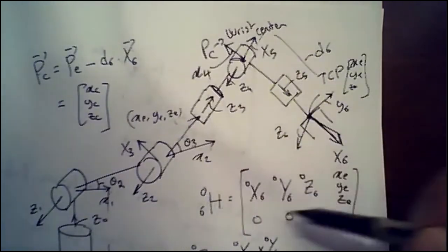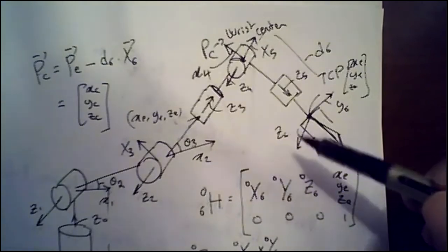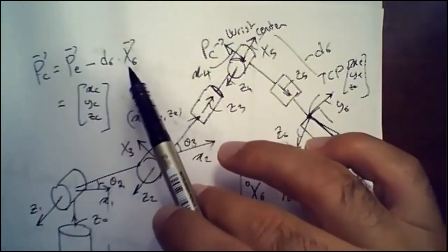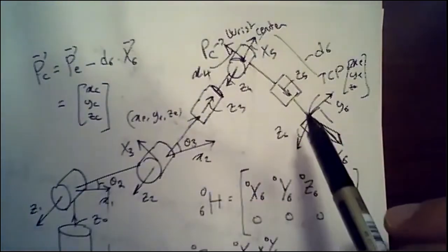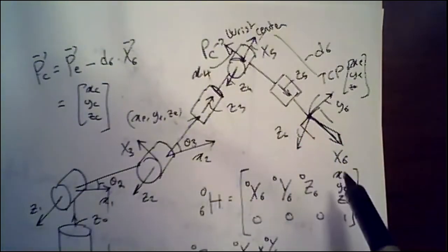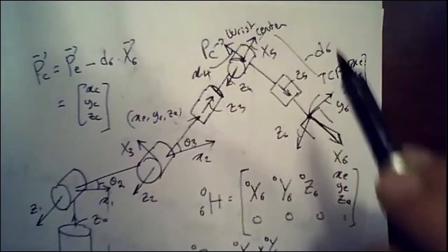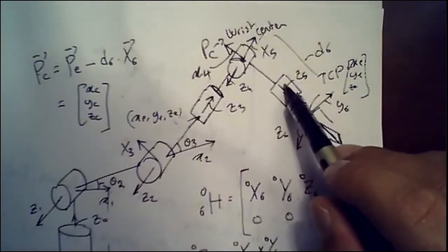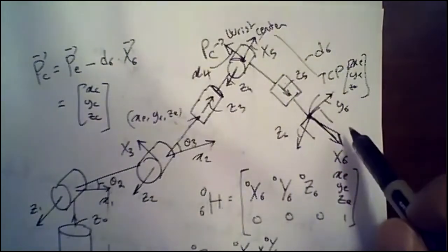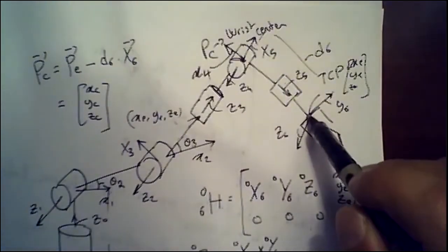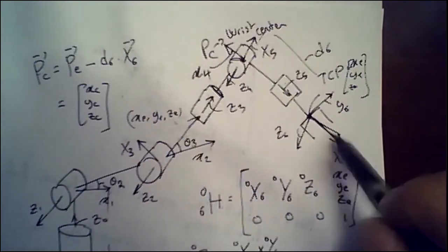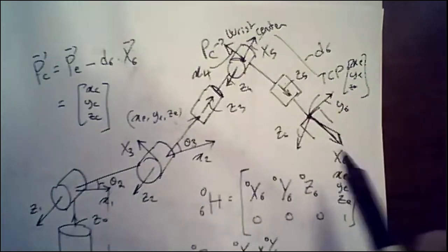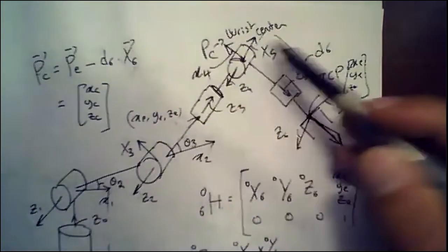Okay, but this will obviously change here if you were to use a DH frame. So this X6 here doesn't have to be X6 if you are using a DH frame. So you want to look at whatever vector that you were to actually put. If you want to use a DH frame here, then this is your Z5, right? We have your X5. Then my Z6 would be pointing instead of X6, right? So this guy will actually be updated to Z6. But now you understand the concept. So these are the angles.